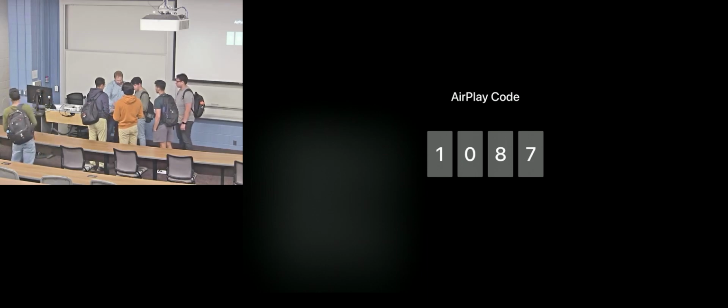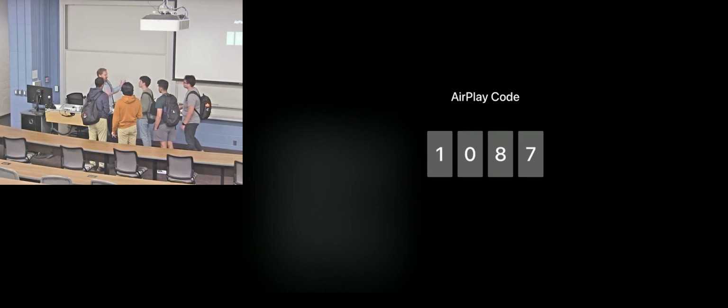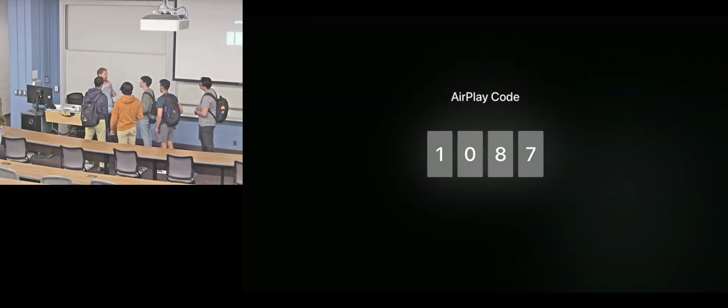I probably went over it too quickly. So you can push any values up there. Oftentimes you push because you just need extra register space because your function needs a lot of registers. So you take R4 through R7, push it up there, and then pop it back down when you're done. So these are always going to be registers, is what gets pushed. And LR happens to be a valid register. So you just put the registers you want. Just remember that the order matters.